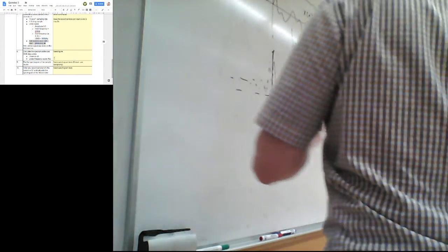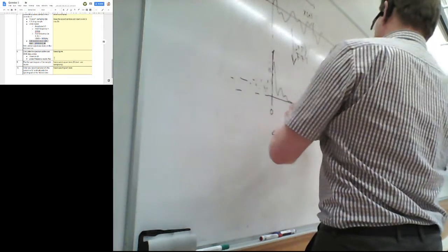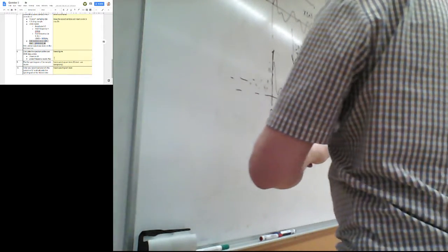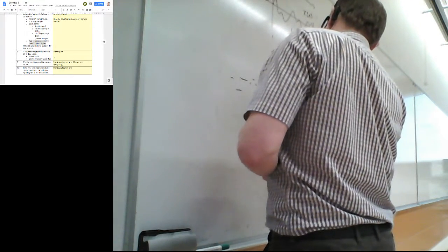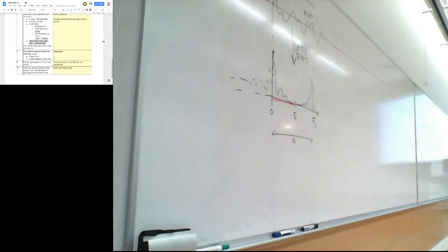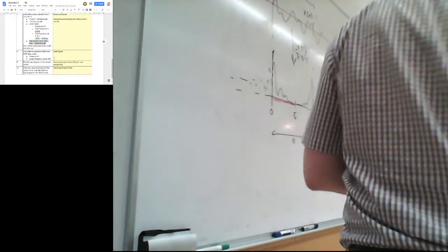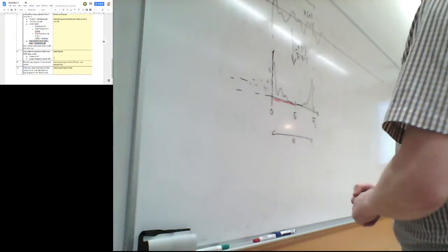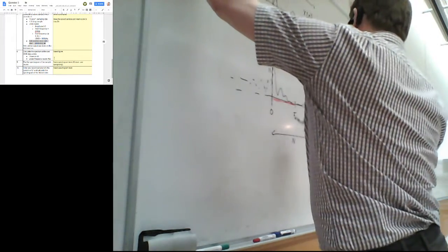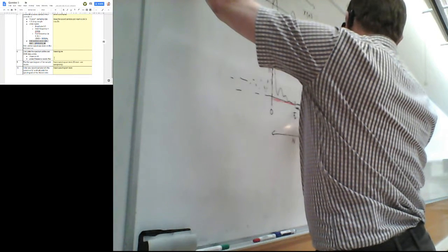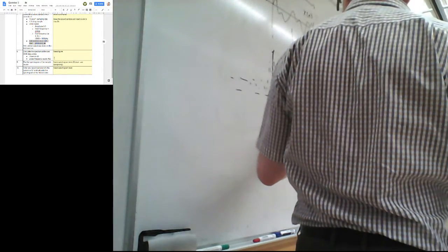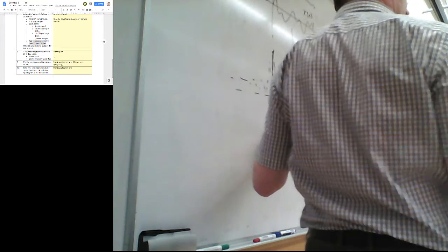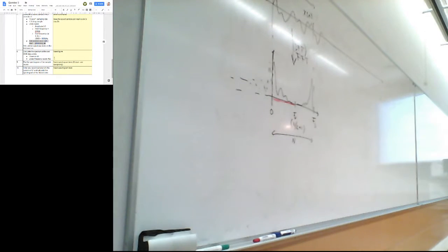The fast Fourier transformation maps this into this, and the only part we are interested in is from 0 to the Nyquist frequency. So the index for the middle point is n over 2 plus 1, because the 0 frequency is on the first element.